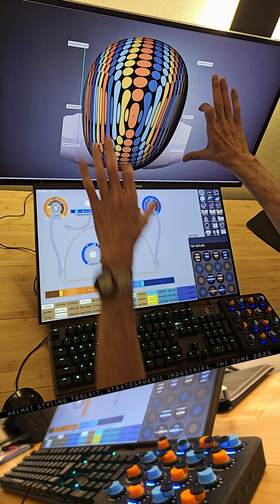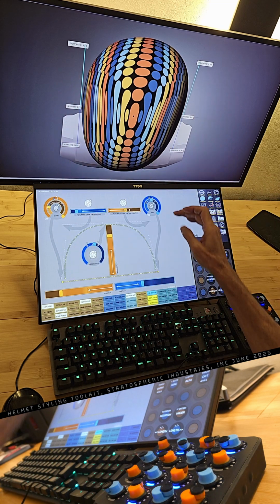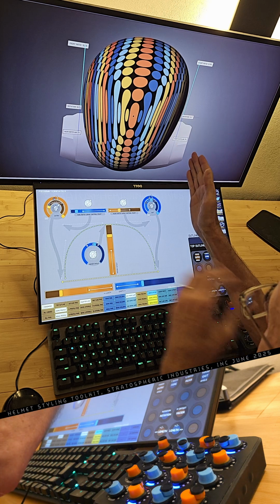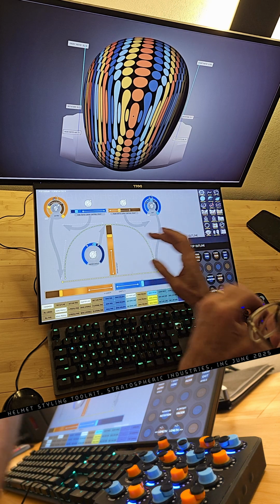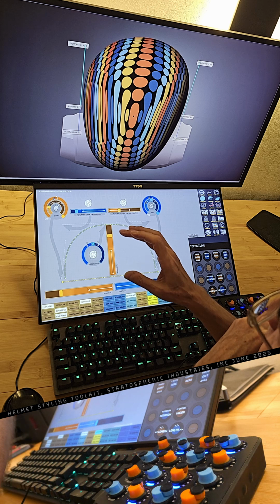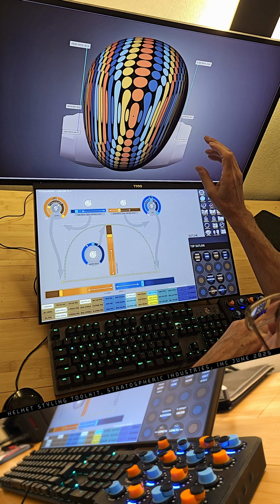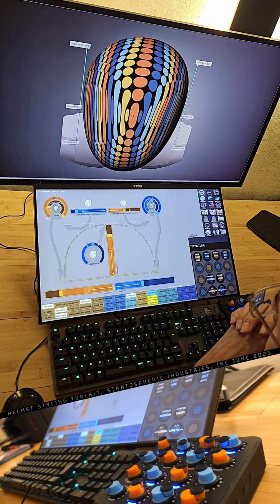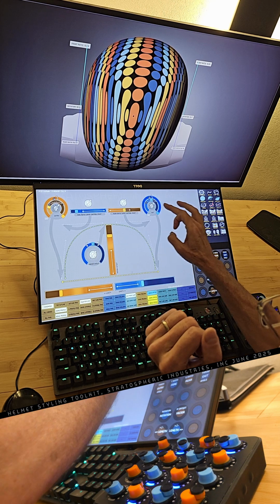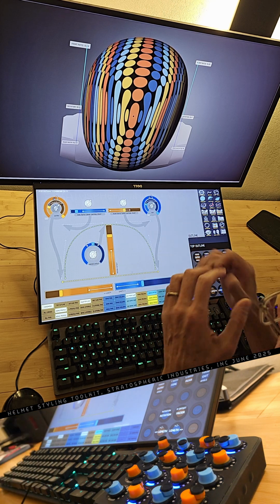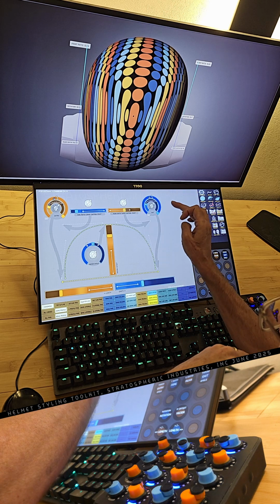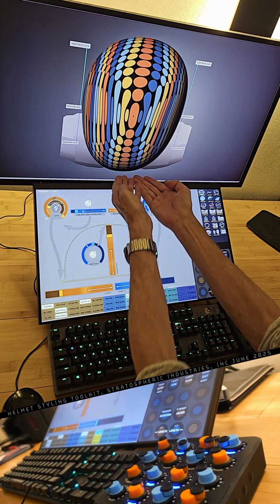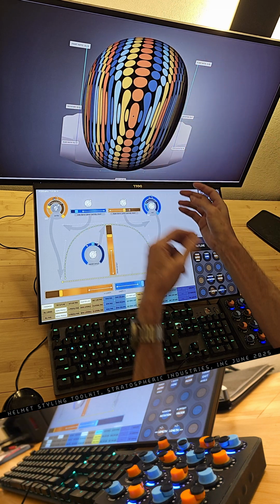These are the control points that control the shape of that helmet. So let's move the ratio inward a little bit here. Becomes a little bit more pin-tailed. Let's go to just a straight flatness and control everything with this here. A little bit further out. And if we want a real narrow ducktail here, we can change the throw of that line. So that's going to bring this in. And that pin is illustrated by this curve right here. This is the magnitude of the curve that's driving the whole shape.